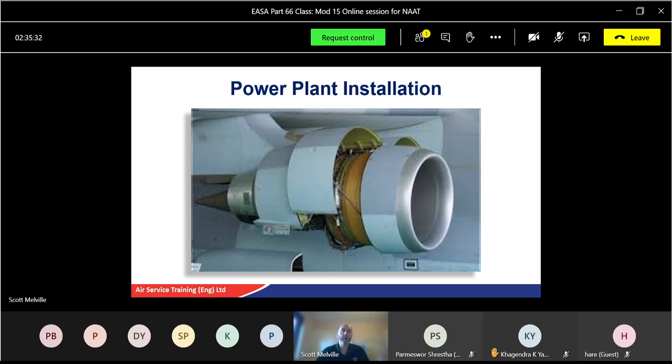the APU bleed valve. However, remember, another way of shutting the APU down: if you switch that switch on before it gets to 95%, that puts too much load, it will also shut down the APU. So there's another one just to remember.